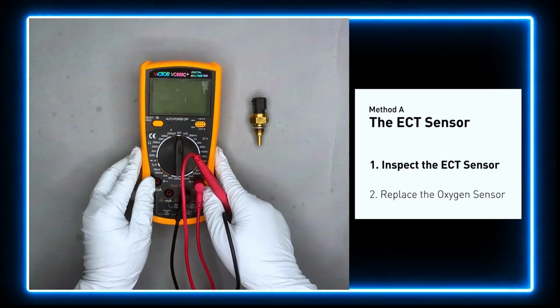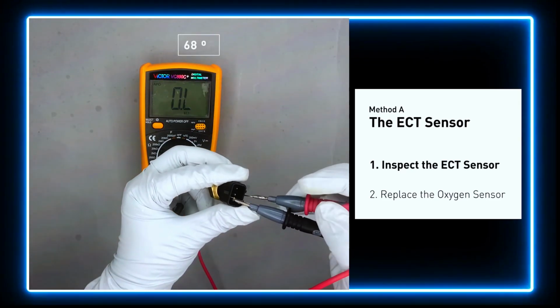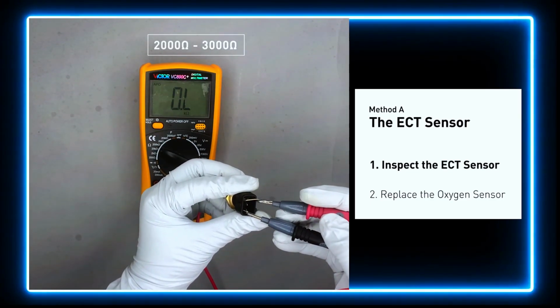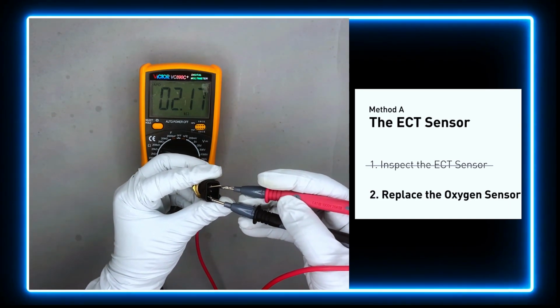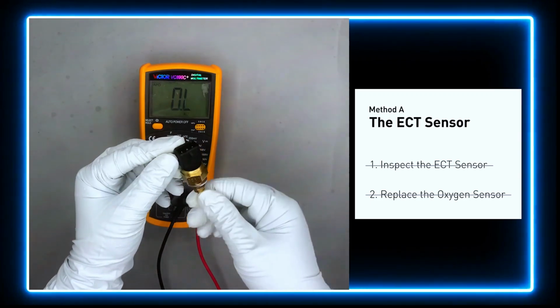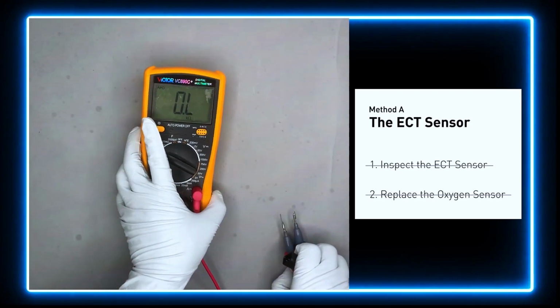Use a multimeter to perform a test on the ECT sensor. At an ambient temperature of 68 degrees Fahrenheit, the sensor resistance should be between 2000 ohms and 3000 ohms. If you do not get a reading, this indicates that the ECT sensor is faulty and needs to be replaced. However, if the ECT sensor has a correct reading, then we will proceed to method B.